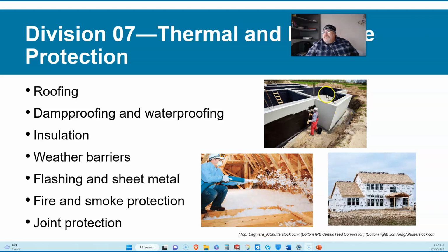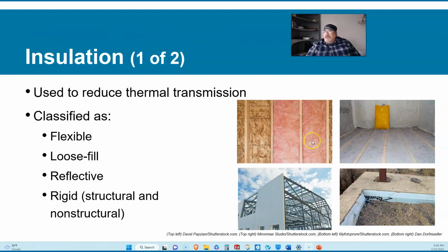Here, you see these are basement walls, and the walls are being coated with a moisture vapor barrier. So water will not penetrate the walls, because where this guy's standing will eventually be filled in with soil. And water will eventually penetrate the soil. And this moisture barrier here will help keep moisture from penetrating the building.